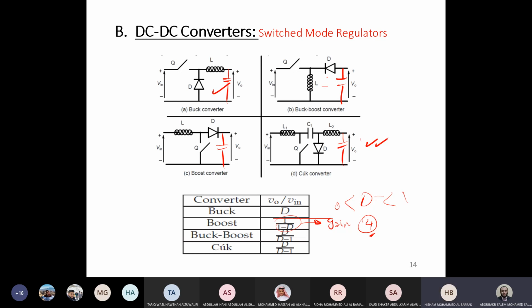Okay. Even in electrical vehicle application? In electrical vehicles, most of the time we use bidirectional converters, not one of these topologies, because as we said, in electric vehicles you need bidirectional power flow. You need to charge and discharge. For instance, if you are going downhill on a ramp, you need to return the energy to the supply. Is it right?